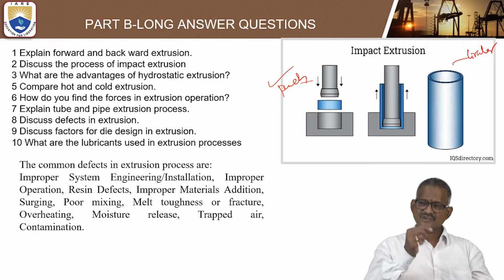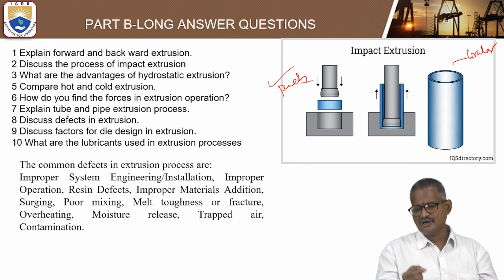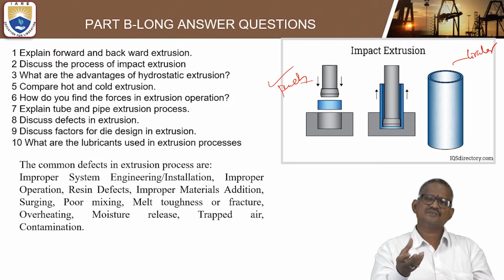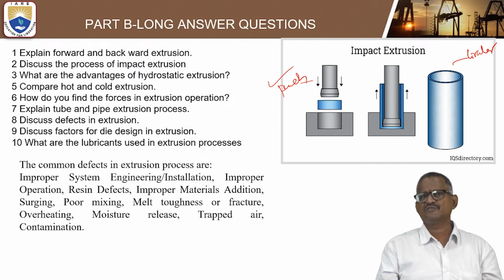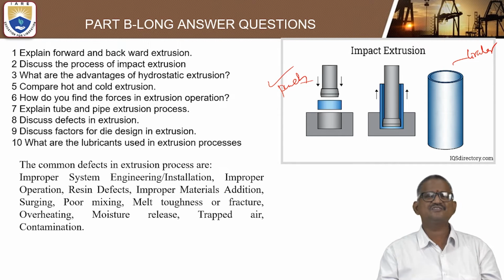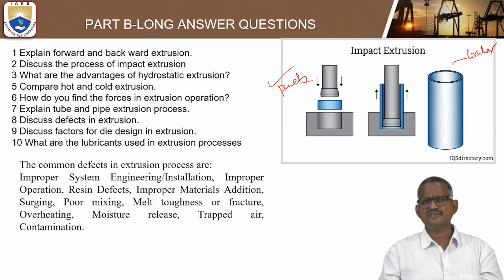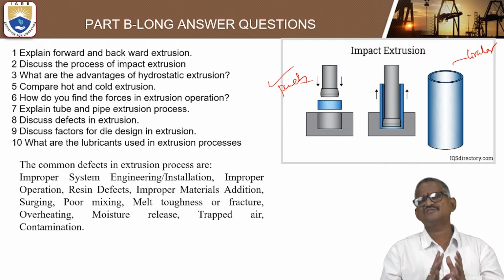So that is why in tube extrusion the outcome diameter can be increased, so that when you apply a small pressure itself, a large amount comes out. Also you can see the advantages of hydrostatic extrusion, where different types of fluids like paraffin and some oils are used in order to apply the pressure effectively without making sound.